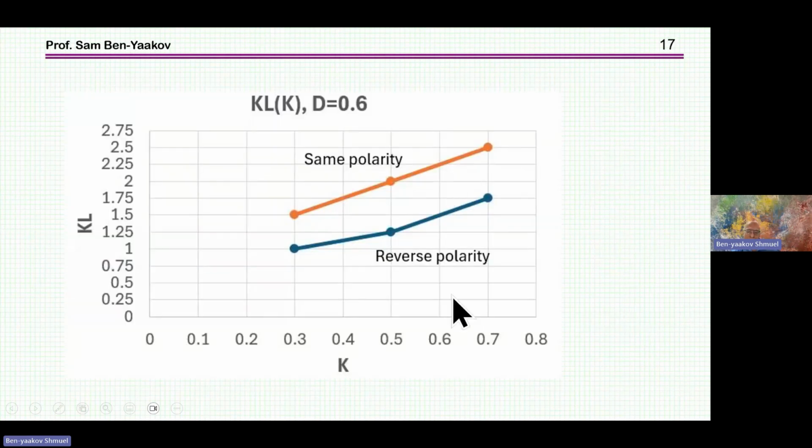So if I compare the two, I see that for different coupling coefficients, I was demonstrating it for the 0.5, I get different values of inductance that I need in the coupled inductor.